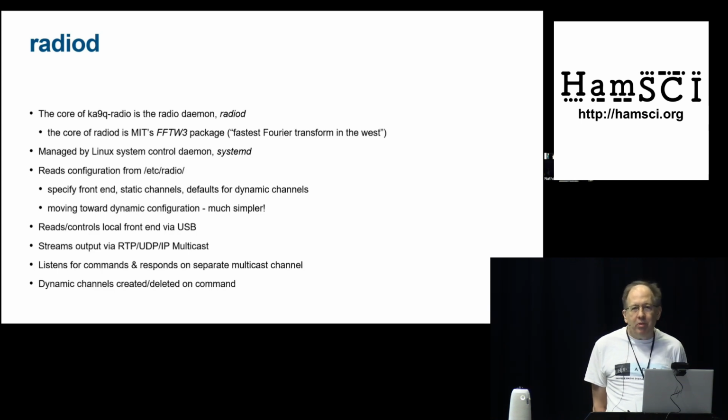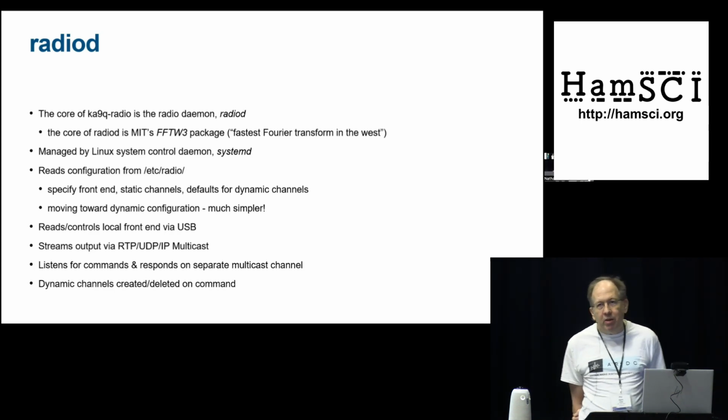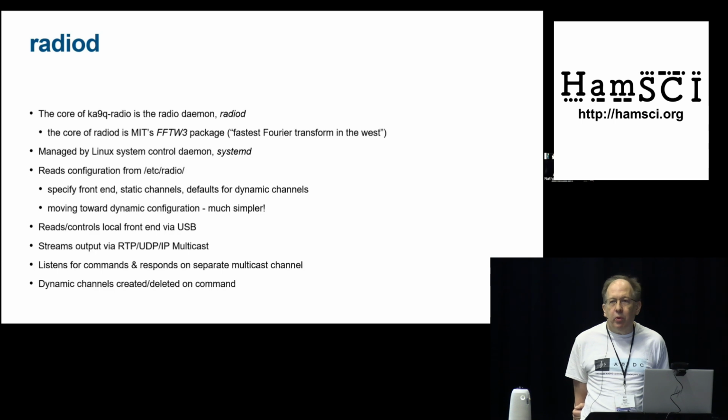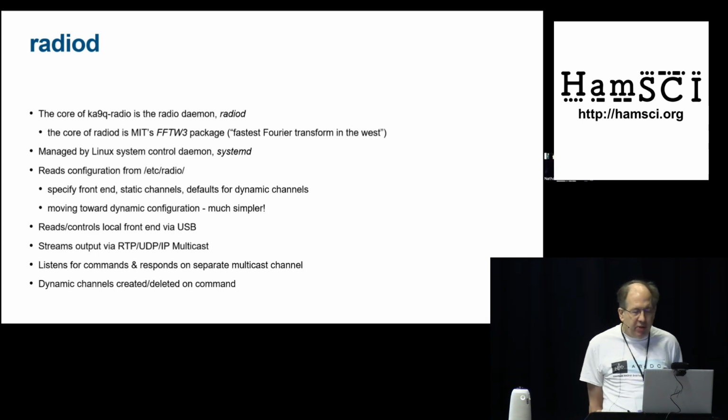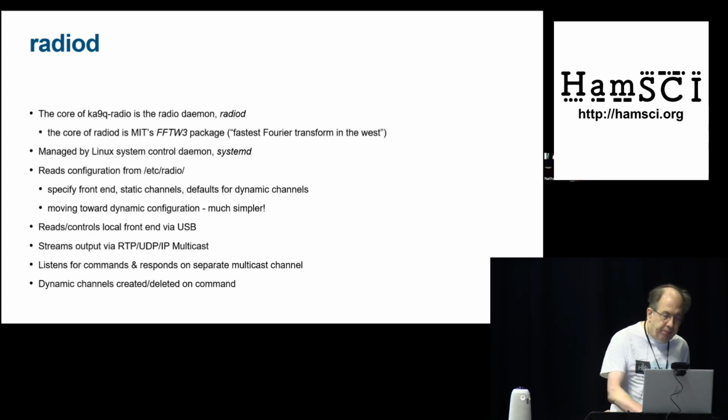I do not currently support the SDRplay because they have a closed library. There is a fork that Franco K4VZ has maintained, but I haven't merged it back in yet, that will support the SDRplay. So everything about Radiod is done over multicast. There are multicast channels with the output streams, and then there's a multicast channel per instance that is used for querying status and sending commands like create a new channel, tune this channel, set the channel filters, and so forth.